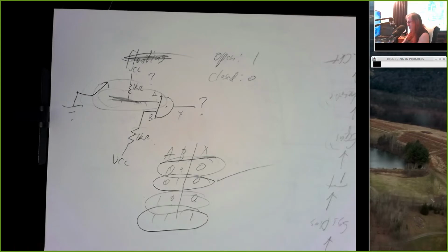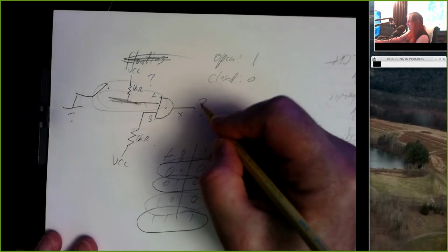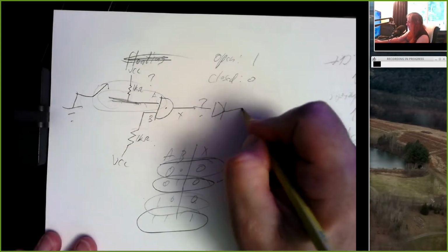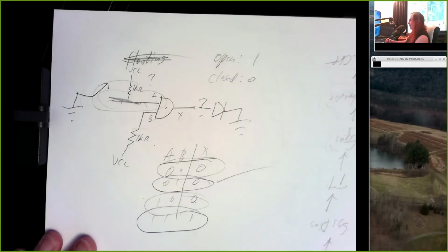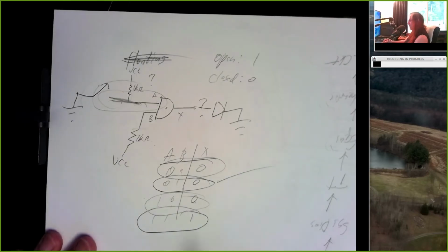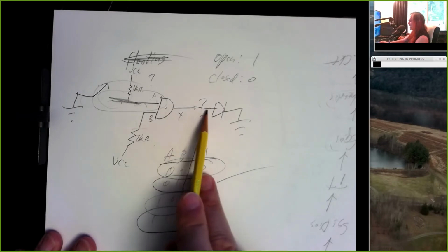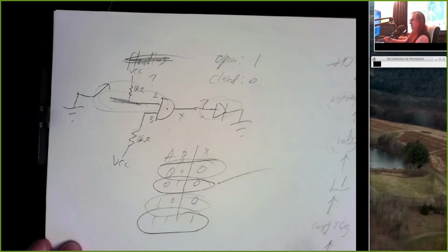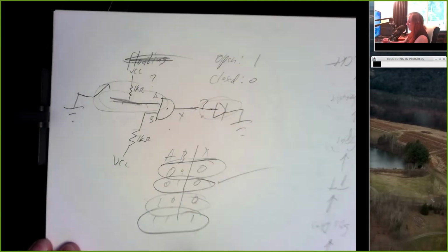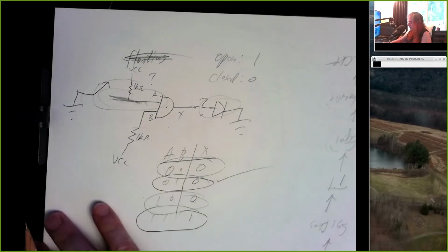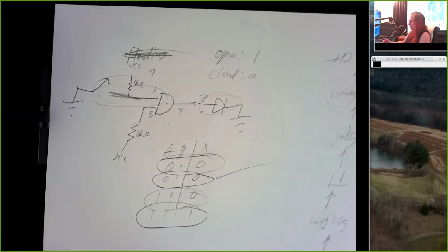In a physical laboratory, for example, when you have an output, you can run it through an LED directly to ground, and it will usually work. Now, if I hook a battery up here, the LED will blow, but if I just use the output of a gate and I don't have the resistor, this will still light up, right? But if your schematic did not include a resistor in here, you would still lose points. Because we've said when you wire an LED, you have to have a resistor in series to limit the current.